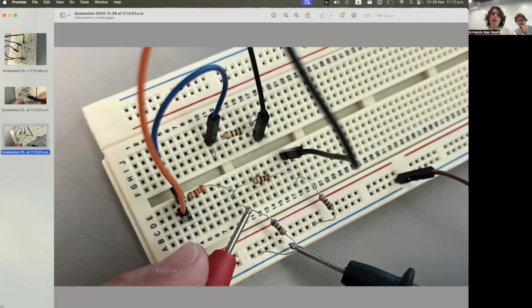And then, as we know, the voltage needs to be measured in parallel. So the thing that we did is just connect both the positive and negative terminals in the circuit just as it is, without removing any cable or resistor, just in both of the terminals of the resistor, and that is how we got the voltage and the current.